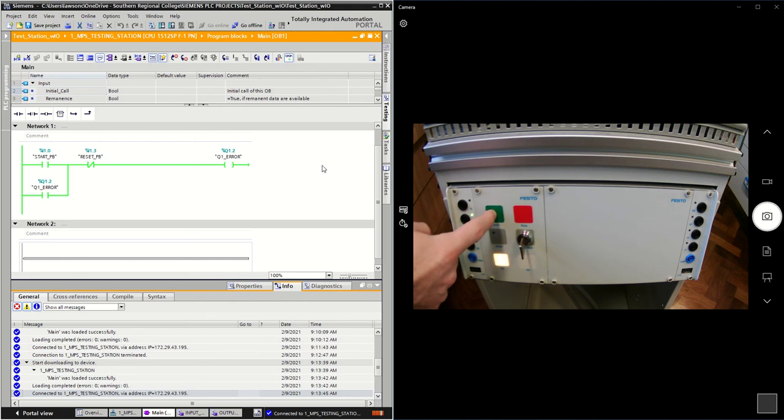So watch, if I take my finger off the start button, see the way we've lost power coming from this pathway, but it's keeping itself running. It's keeping itself self-sufficient internally in the code. It's using that link internally to keep itself running, using the output as an input to itself. So now the only way to break that is to operate this push button.